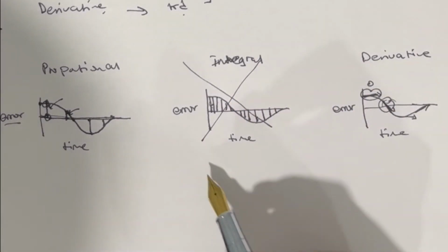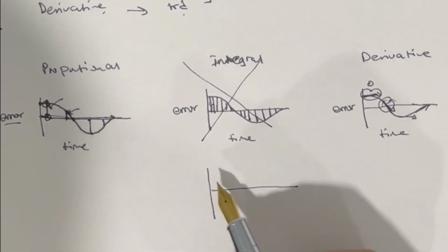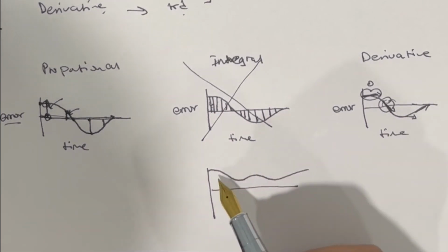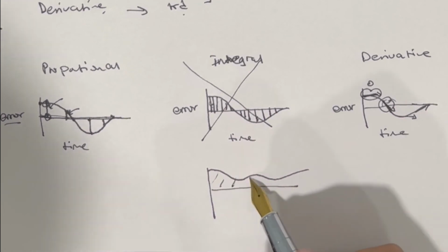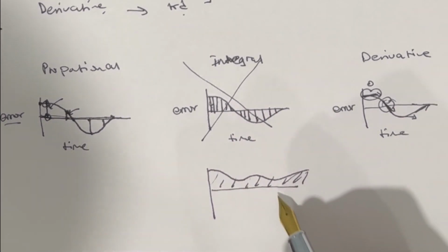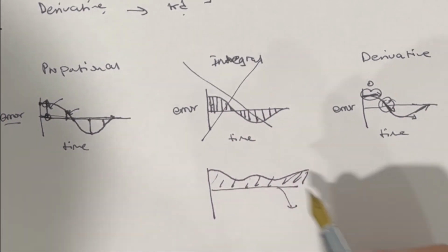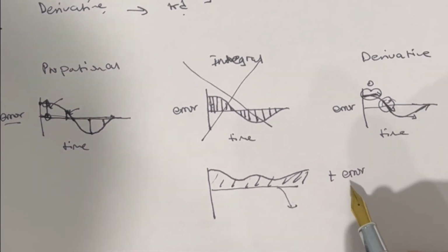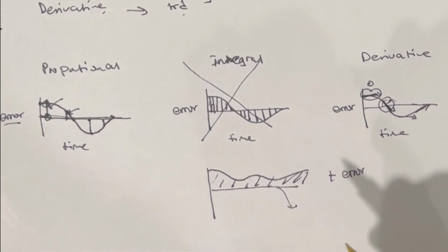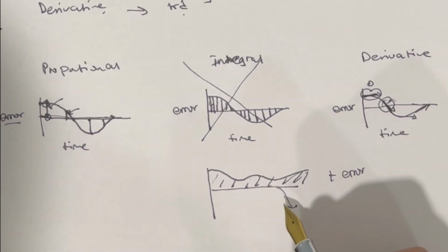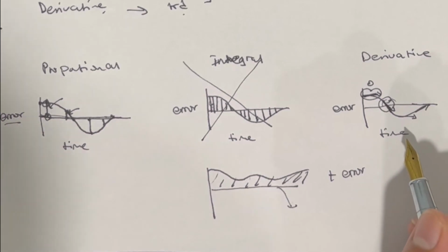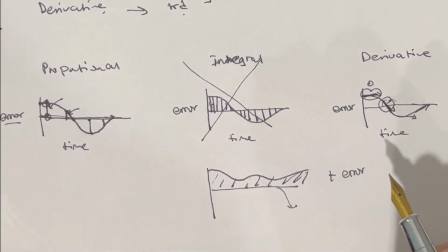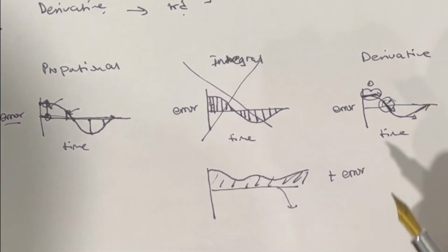And so this means that realistically an integral graph for a line follower with robotics would look something like this. And this would mean that the integral is always going to be positive over time, because it's never crossing this axis. It may cross a little bit, but the net result would be a positive error. And so this would lead your integral to accumulate over time, and that would cause your robot to have to adjust for this by changing either the proportional or the derivative part of this program, and that would lead to your line follower being very jerky. And if you have a jerky line follower, it's going to end up being inaccurate.